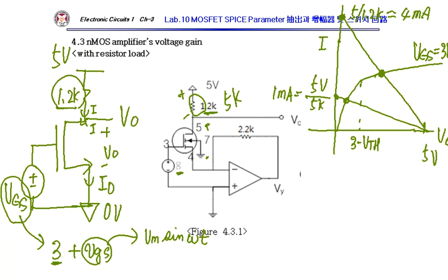Yeah, this one sees the large signal characteristic, I think. I can change this voltage, sweep this voltage. For example, I can sweep. When this input voltage, the gate source voltage, is smaller than the threshold voltage, the current characteristic looks like that. My operating point is here.